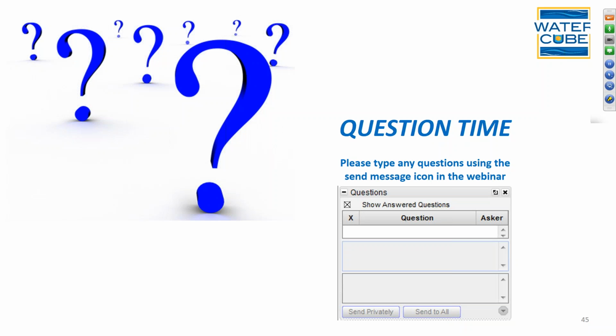So the question specifically, Diana, is the utility, if I could rephrase it, of using an ADCP in reservoirs for bathymetry? Yep. For accurate depth, yeah. So, exactly right. Just to clarify for everybody, as any transducer emits a pulse, as we go through density layers, it's going to shift, and as it shifts, the depth that it provides is not going to be the true depth. And so you correct that.